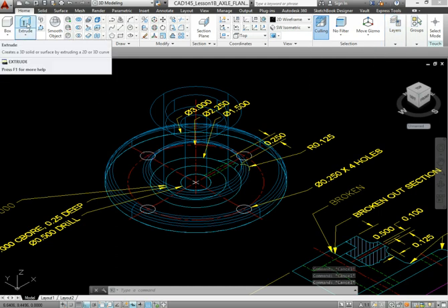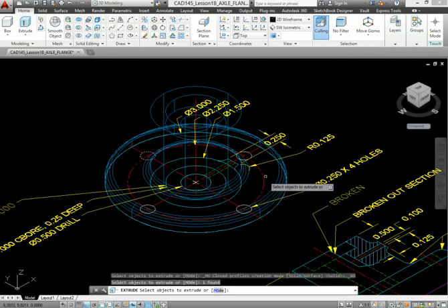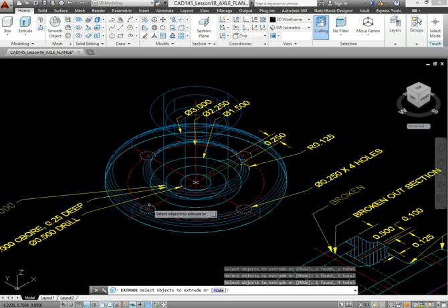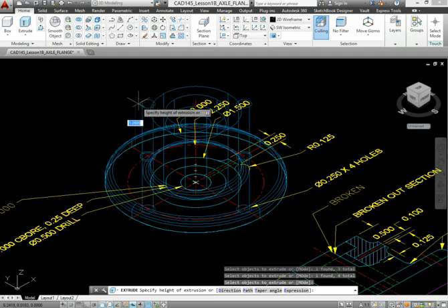So pick extrude, select your 4 holes, click on enter. You will see automatically you could use extrude in a couple ways. You can just extend manually, up or down, or you can type in distances in that blue area you see there. Because we don't concern ourselves with the height, just extrude at any length above the base of the part.